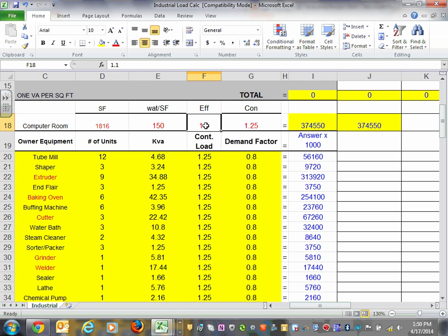Obviously, when you size your servers, guys, they're going to be chewing the electricity. You need to allocate. They're going to go through transformers, and they're going to go through a conversion AC, DC, AC again. And so there is a factor of efficiency. Safety factor would be 10%. So that's where that efficiency factor of 1.1 comes in, I'm adding 10% because of efficiency to this load.